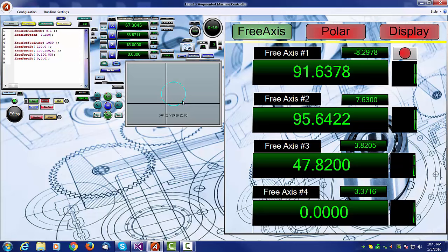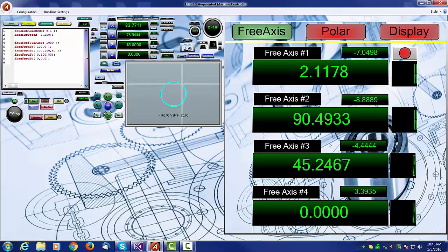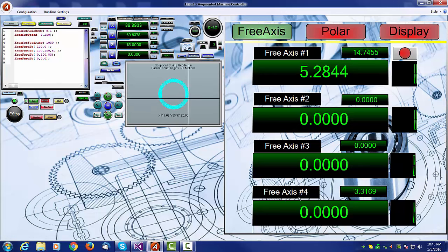So while we're cutting our spiral pattern, at the same time, this second version of 4 axes is cutting a box. Now, this would not normally be used for cutting, and because of this, I don't store it in the continue processor, for example. I may at some point store it there. But at the moment, it's just used as something you would use for perhaps spindles as well as tool changers, because it gives you 4 axes that you can manipulate in a trajectory planned fashion.